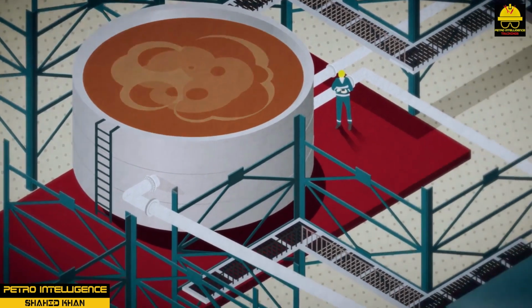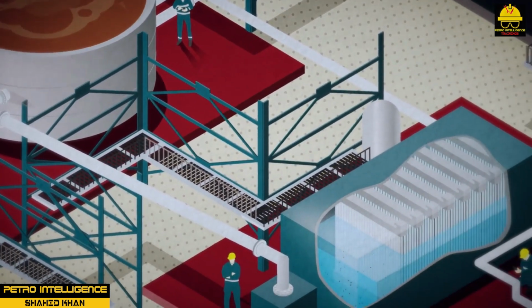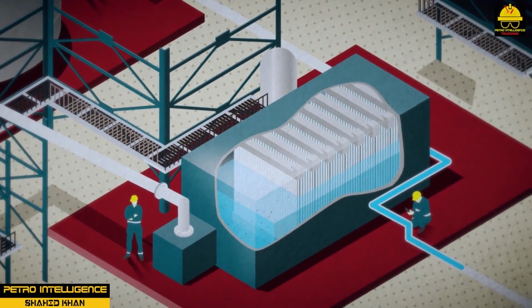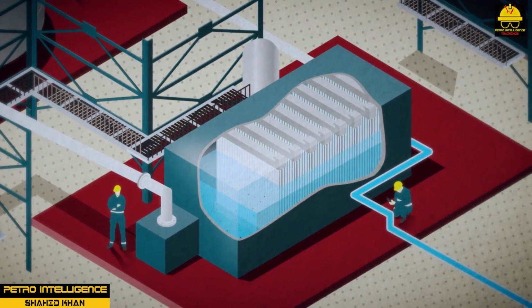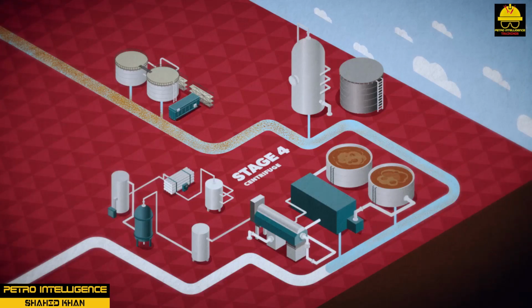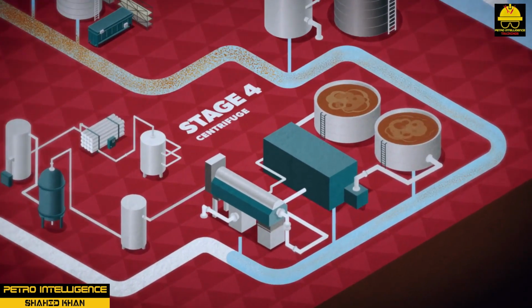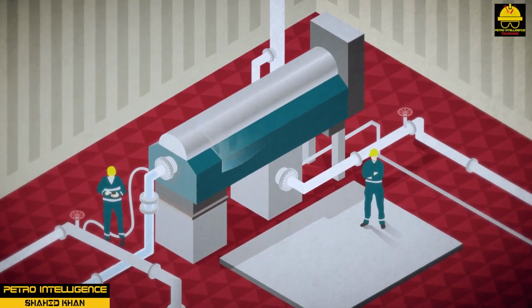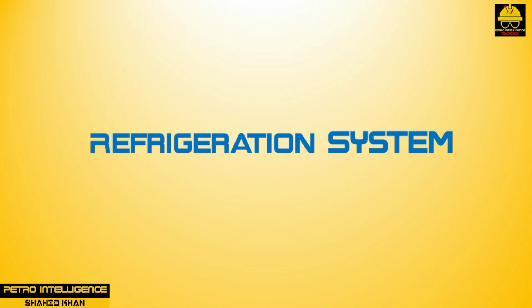All contamination in the sewer water is removed in the waste treatment system before the water is returned to surface streams or lakes. Sanitary sewer systems are generally routed to the waste treatment area, where they are treated to remove contaminants. Sewer drains are trapped via a liquid seal in such a way as to prevent gases from backing up into the drain lines.